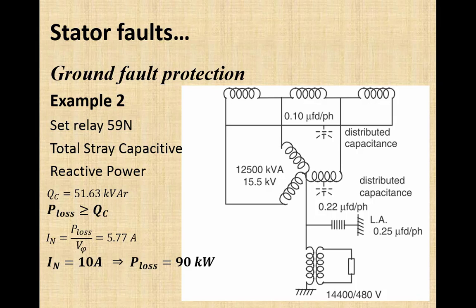Remember, the distribution transformers here are pole mounted transformers. These transformers can be overloaded beyond their rating up to 20% for a short duration, and that duration will be a few minutes. So it means if we divide this 90 kilowatt by 1.2, then we will get the power rating of this transformer, which is 75 kVA. So this transformer can be overloaded up to 90 kilowatt for a short duration. So that is the method to determine the rating of this power transformer.